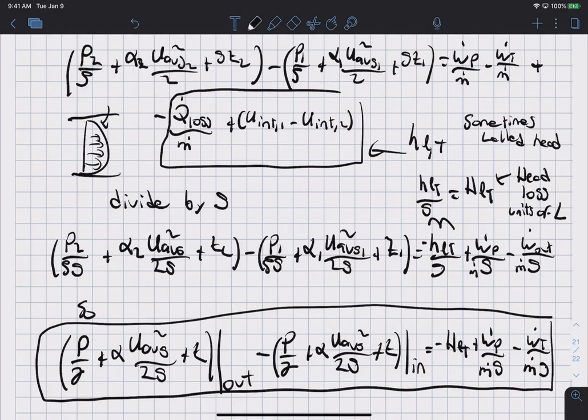Okay, and so essentially physically what's going on is, if we draw the pipe and the velocity profile, there is actually a friction between the layers of fluid as they slide over one another, and just like if you take friction from, say, rubbing your hands together, the heat builds up, and so all the power that you're putting in rubbing your hands is actually going into heating your hands, and that goes into, if you draw the control volume around your hand, there is a heat loss because your hand is losing heat to the outside, to the air above it, and also the temperature of your skin on your hands also changes.